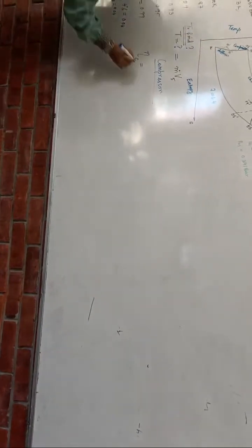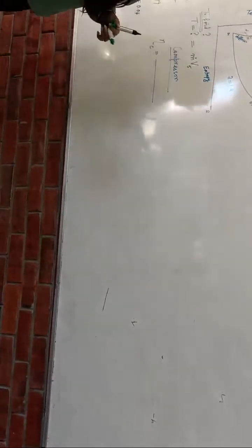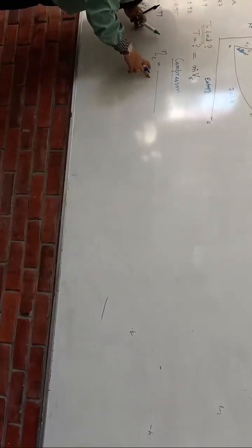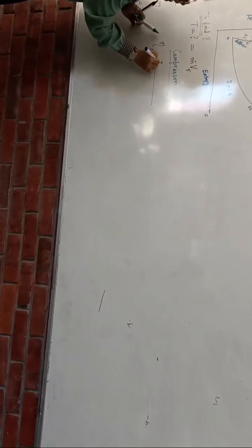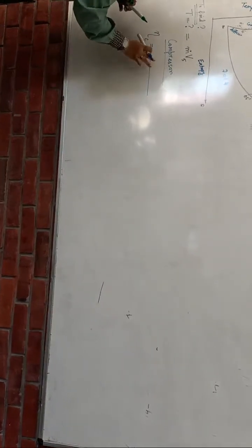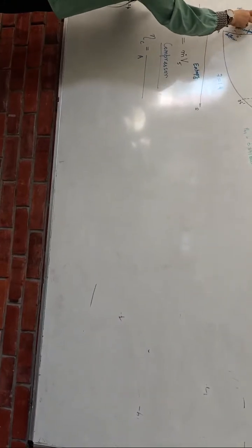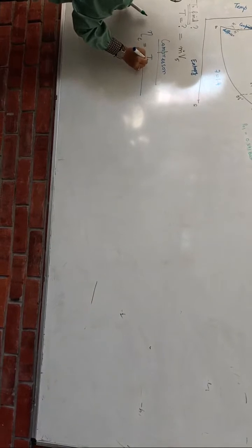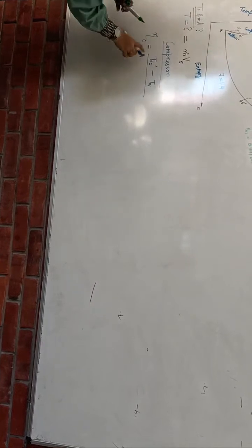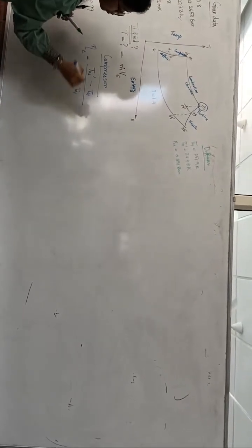That's the best part. When they have given efficiency, we'll use the efficiency. Now, again what is the formula of compressor efficiency? Temperature difference between the isentropic relation over the actual relation. That is, we say I by A, in short, to remember it. So what is this I? I is the temperature change of the isentropic. I will take from the higher value to the lower value. So, T02 prime minus T01. Now, actual becomes T02 minus T01. Simple.